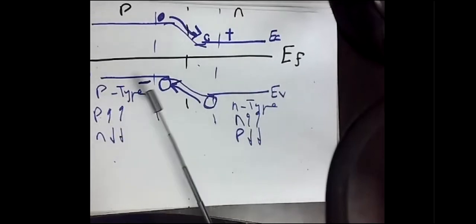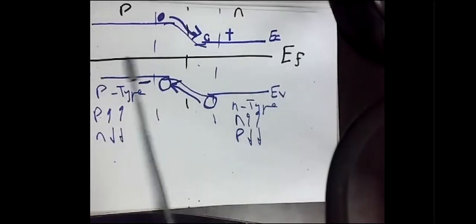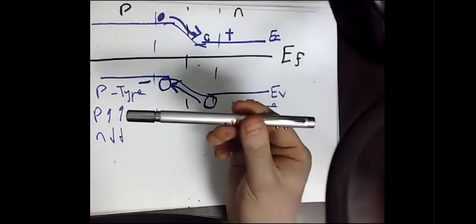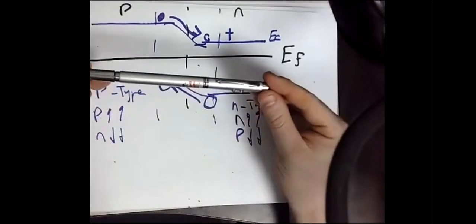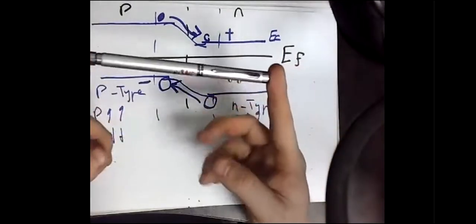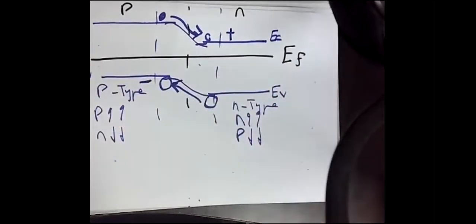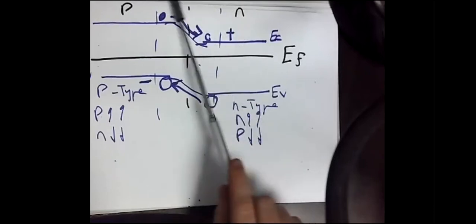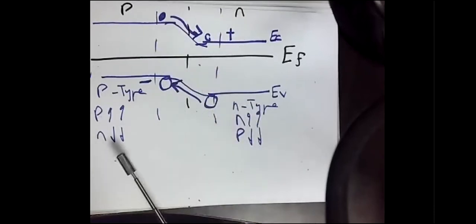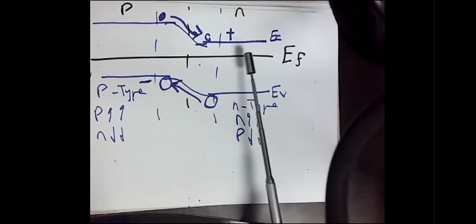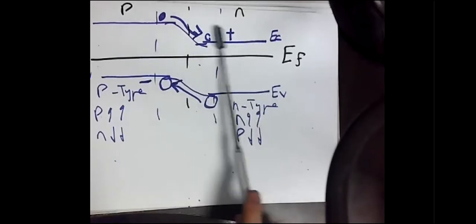And we already mentioned that whenever we say this, it is under thermodynamic equilibrium. For example, you have a piece of diode. Do you expect that if you hold this diode in your hand, you will find a current through it? Of course not. There is no potential source. Whenever there is no potential source, there is no current. So that means that the total electron current is equal to 0, because the drift current is cancelled by the diffusion current.